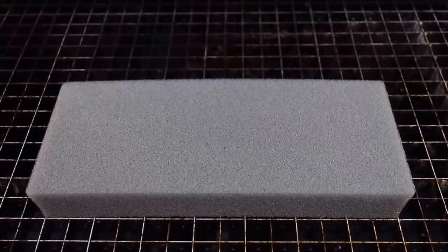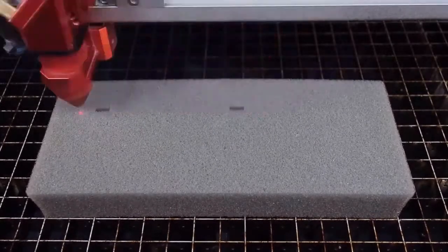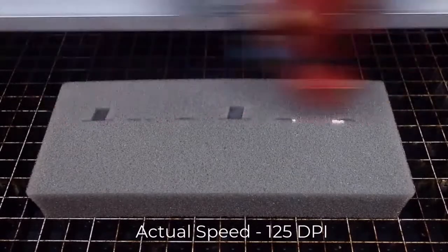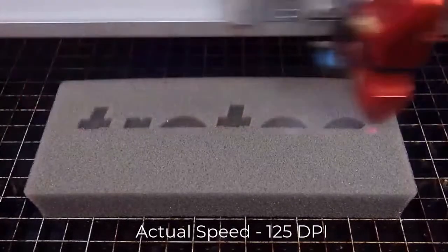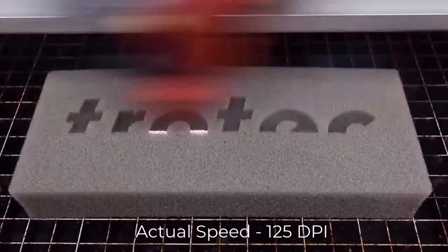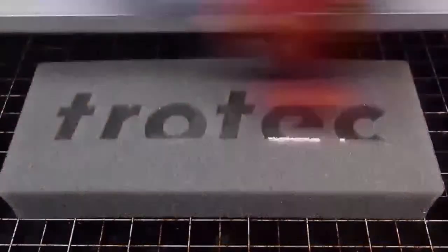So here is a standard polyurethane foam for engraving, and you can see here as an example how the material forms. And this is only run at 125 dpi, so very low resolution. This is about a 3-inch by 6-inch block of foam, 1.5 inch cut out sheet, but you can see the contrast is outstanding. Good contrast, and this is actual time.